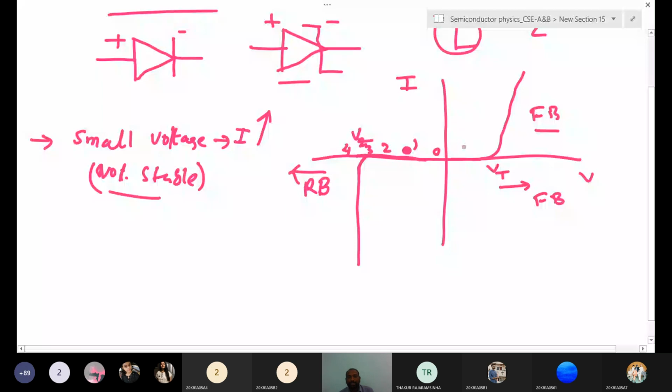That is very less, minus 12 to minus 15, or minus 13, like that. It's a very small current, that's why it is negligible. Here also, in reverse bias up to a certain breakdown voltage, there is very little current, also around 10 power minus 12 to minus 13. That you can say is the saturation current.